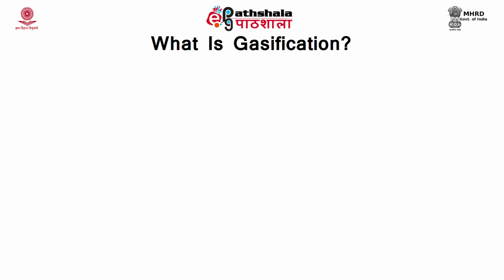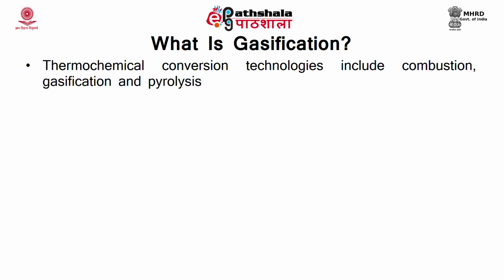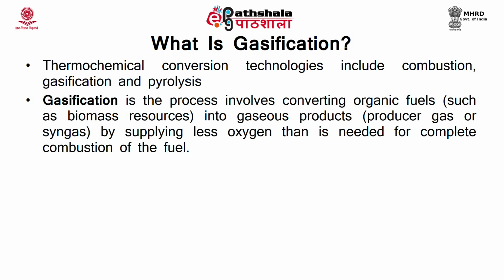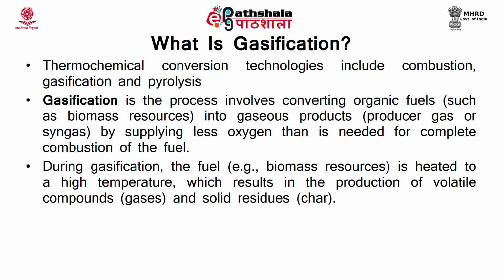Now, what is gasification? We have already seen the thermochemical conversion technologies include combustion, gasification and pyrolysis. This produces energy in different forms. Gasification is the process of converting organic fuel into gaseous product, mainly the producer gas or syngas, by supplying less oxygen than is needed for complete combustion of the fuel. During gasification, the fuel is heated to a higher temperature, which results in the production of volatile compounds, that is gases, and solid residues, which is char.